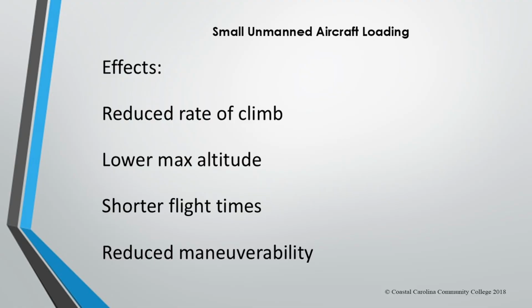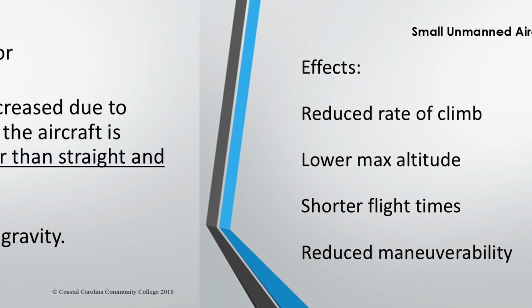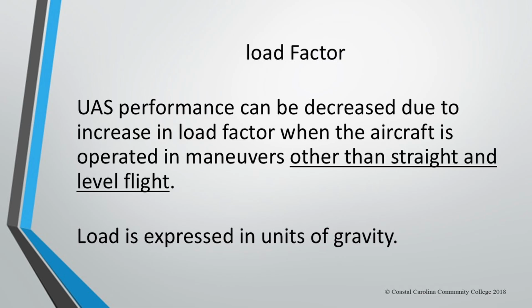Well, it has a reduced rate of climb, a lower max altitude, shorter flight times, and reduced maneuverability. The drone performance can be decreased due to an increase in the load factor when the aircraft is operated in maneuvers other than straight and level flight.